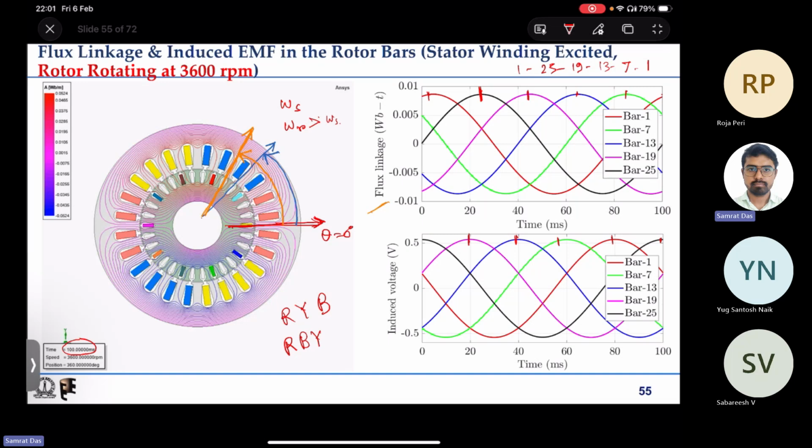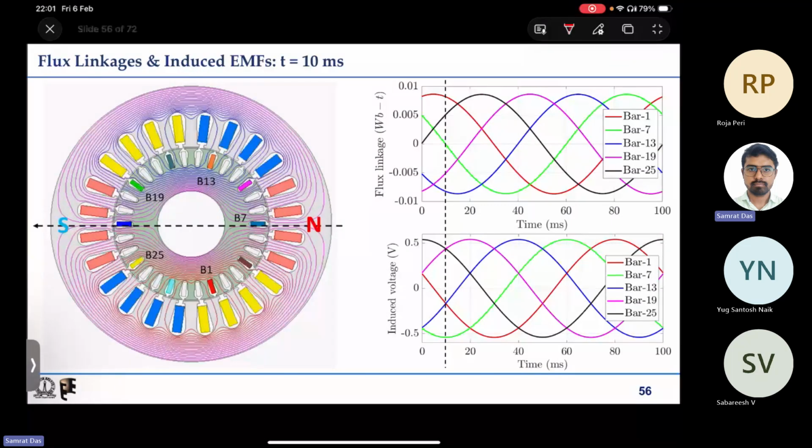That is why in an induction machine, if you give some phase sequence and the rotor rotates in the anticlockwise direction or some direction, if you change 2 lines and connect it and give supply again, then it will rotate in the opposite direction, because simply the direction of rotation of the magnetic field is getting changed, right? So in this case let us try to see one by one what happens.